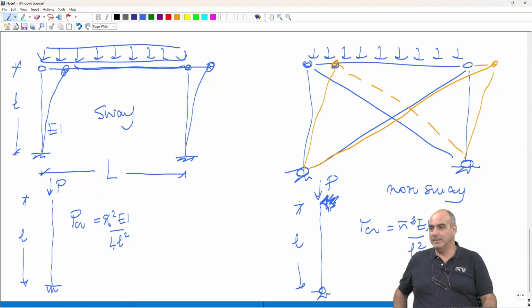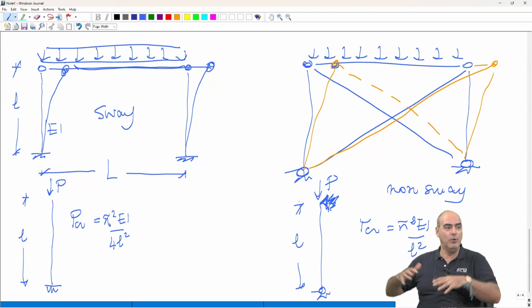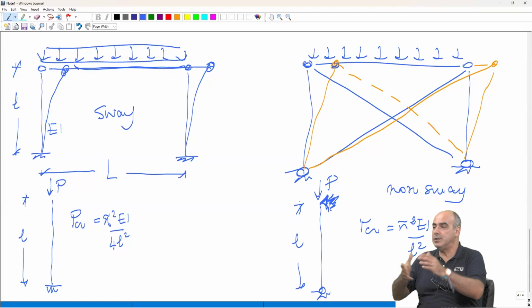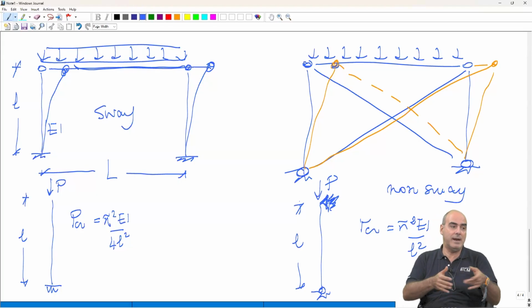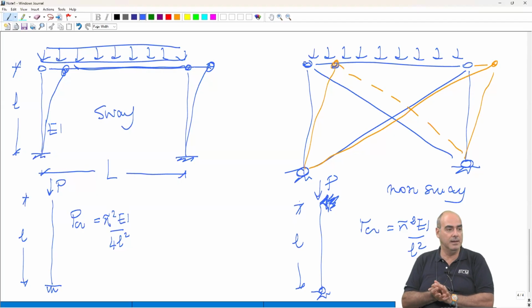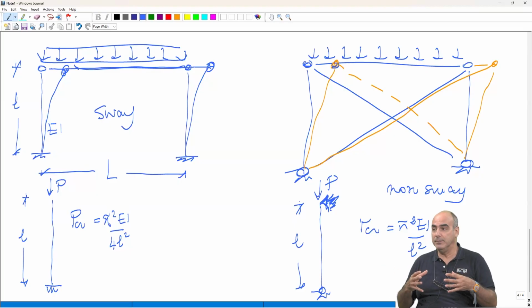Or, you know, you have decided that you are a good employer, and on the top, you want to create a recreation space for the workers. But this means that your roof was designed only for snow loads, which is 120 kilos per square meter in most cases in Italy. And now if you put a recreational space, you can go up to 4 kilonewton per square meter. 4 kilonewton is what we call congregated crowd.